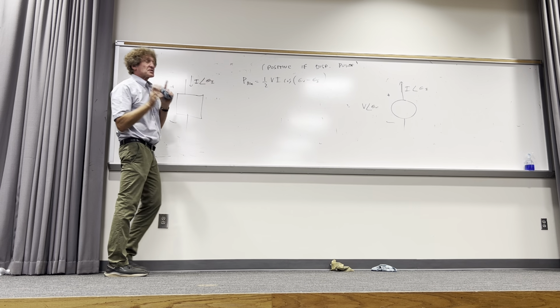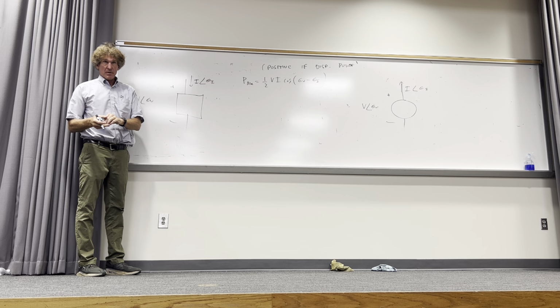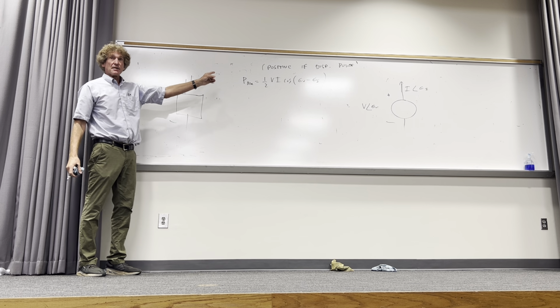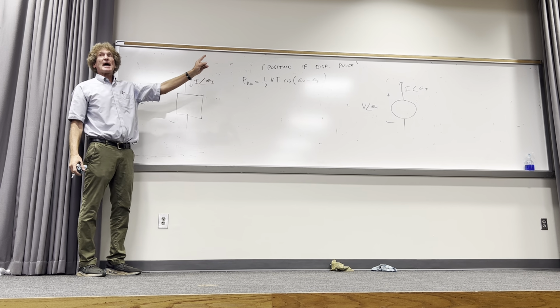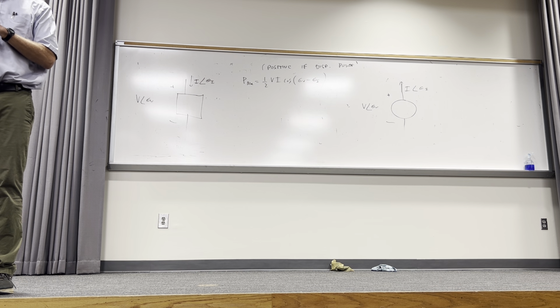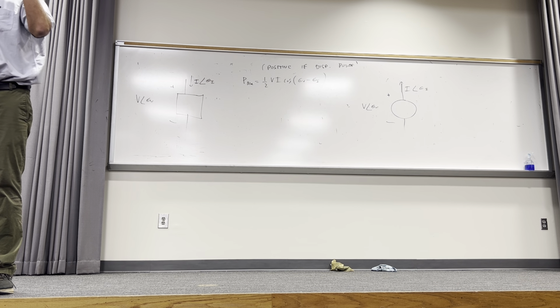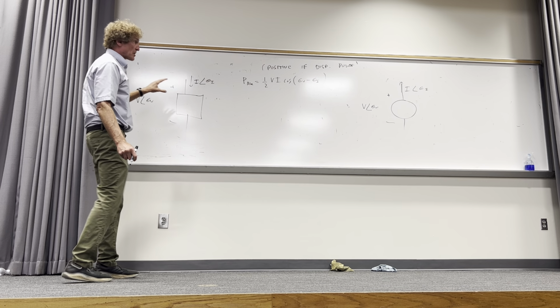However, if it is supplying power, this will be negative. Do y'all follow me? As a matter of fact, what always happens, if you sum the powers associated with all the elements in the circuit, including the sources, you get 0. The net power supplied, which will be negative, is equal to the net power dissipated, which will be positive. You all follow me? Now this is the way the symbols work.